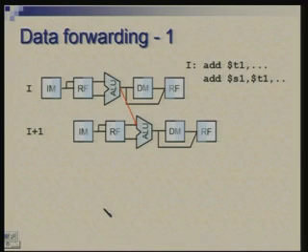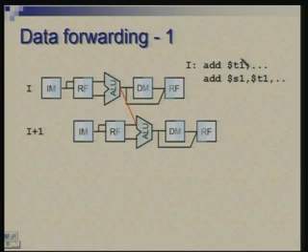So, they are not immediately reading, but the instruction which is following, and this would require some analysis by the hardware. The controller will basically have to see if there are two consecutive instructions of this kind, where the destination of one is the source of other, then we simply allow this, we activate that path, right.